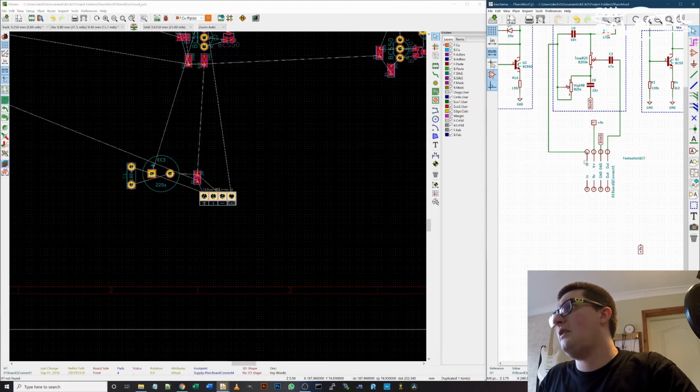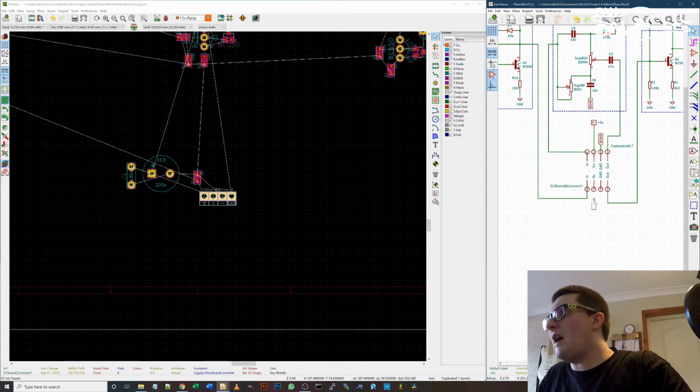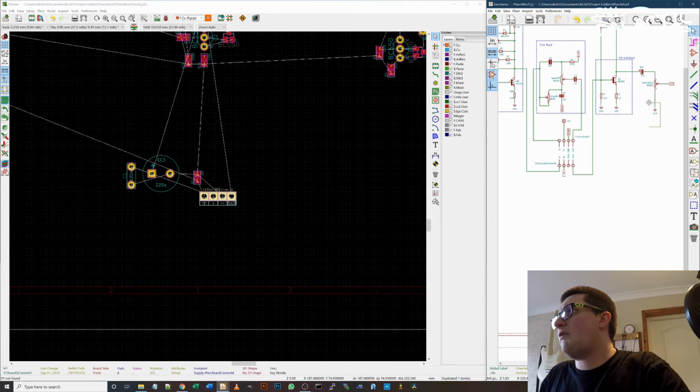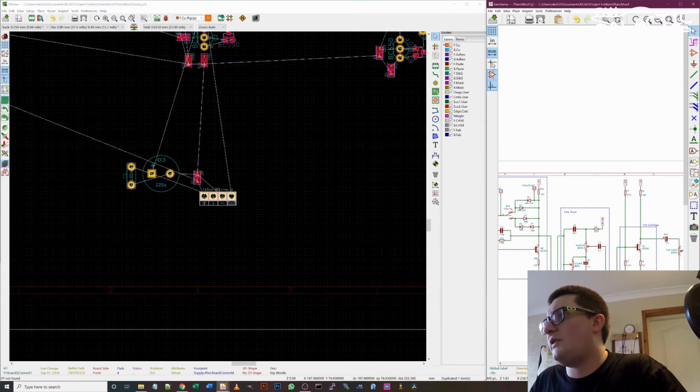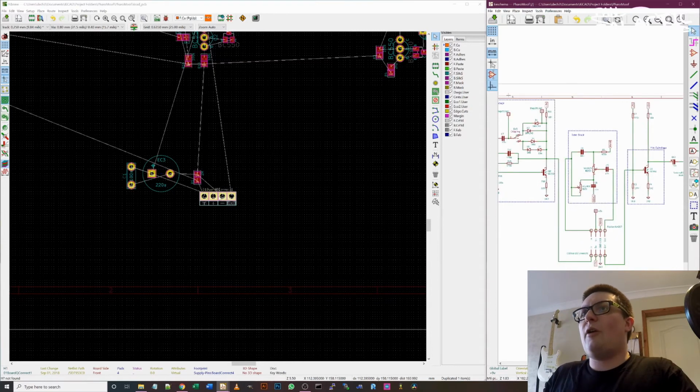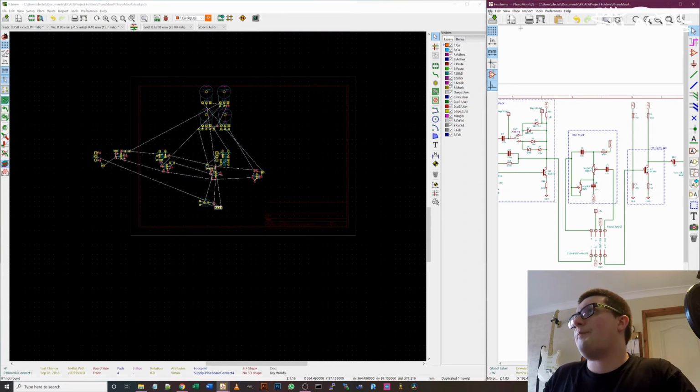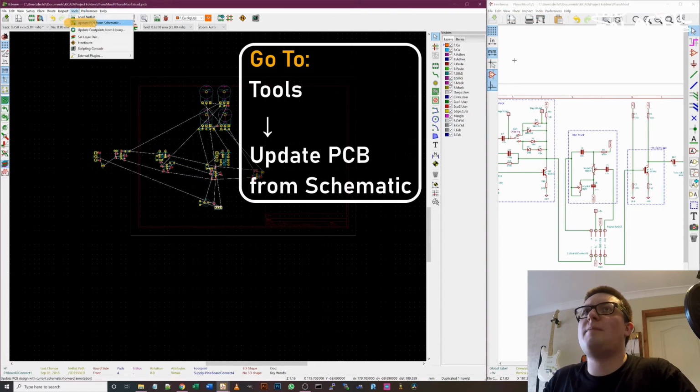So we've got our output here goes into this circuit. We've got 9 volts, we'll go to 9 volts. Our grounds will connect together, and our outputs will go to the output. So all we need to do now is add the wires and add this 9 volt flag here, and we'll also add the ground flag. So now this tone section of the circuit is a removable daughter board rather than a permanent part of the circuit. Unfortunately now this does not match our schematic, so I'm going to save it. You can generate a netlist again, or you can update PCB from schematic.